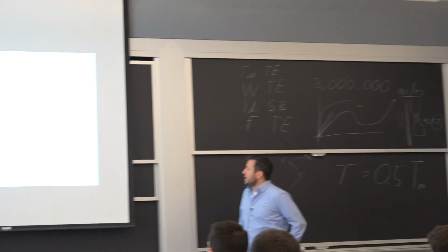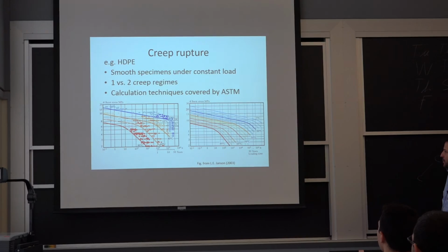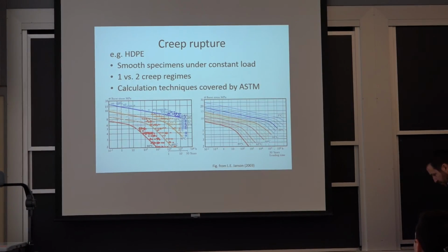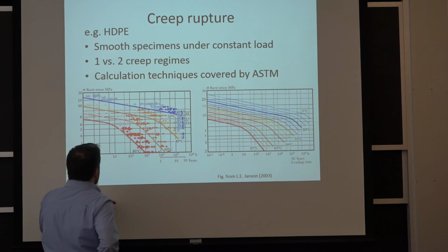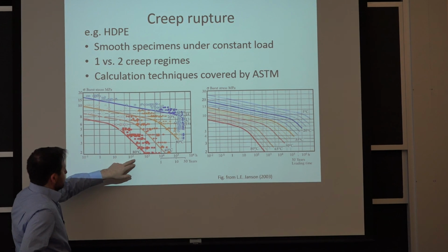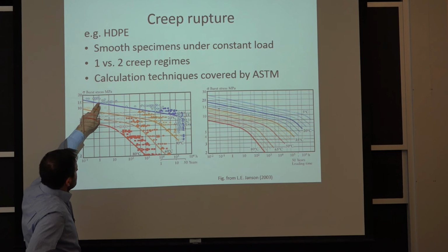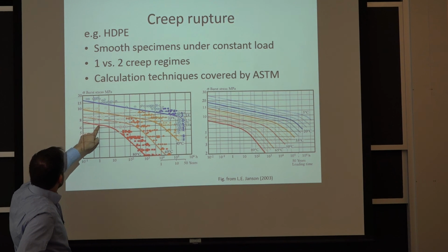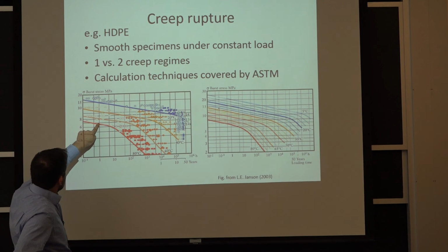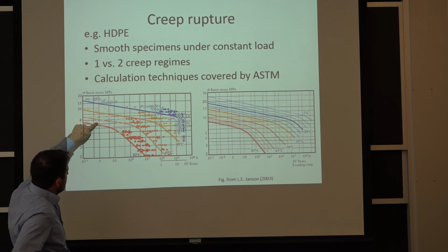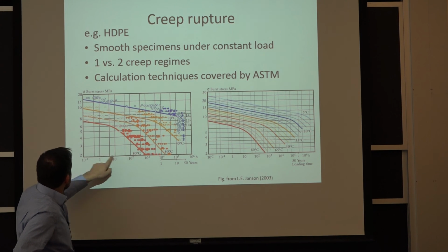Okay, so all this is showing here is if you're thinking about a pipe that's going to be used for a very long time, well, when you test in the lab that you're going to do in 1 hour, it gives you, let's say on this one, 6 megapascal or 7 megapascal of strength, but if you waited and you ran your test for about 4 months, there will only be 2.